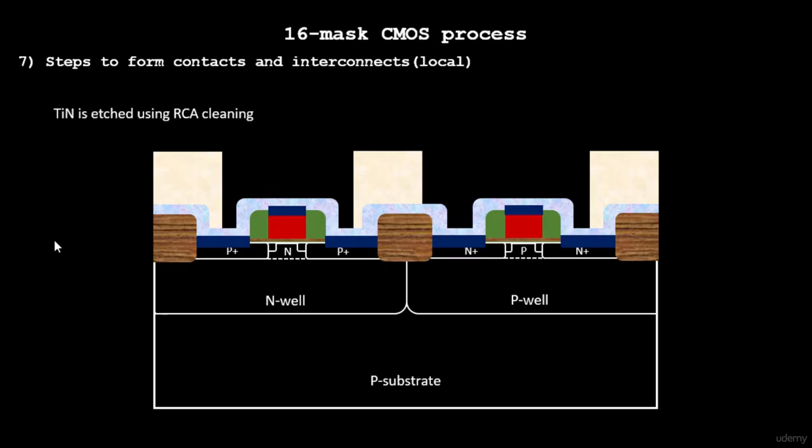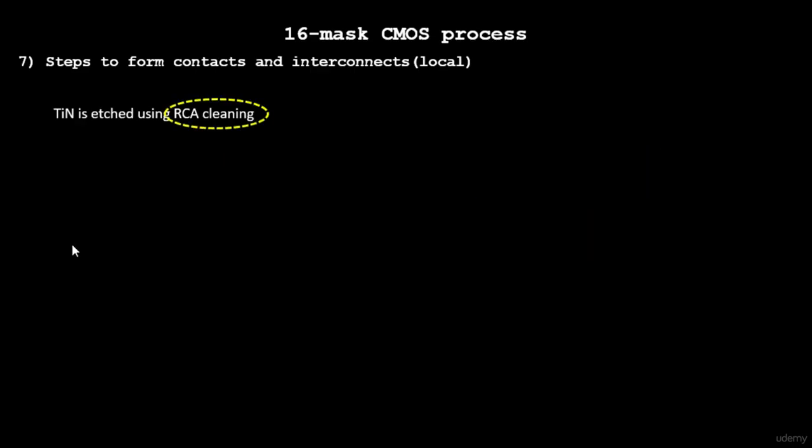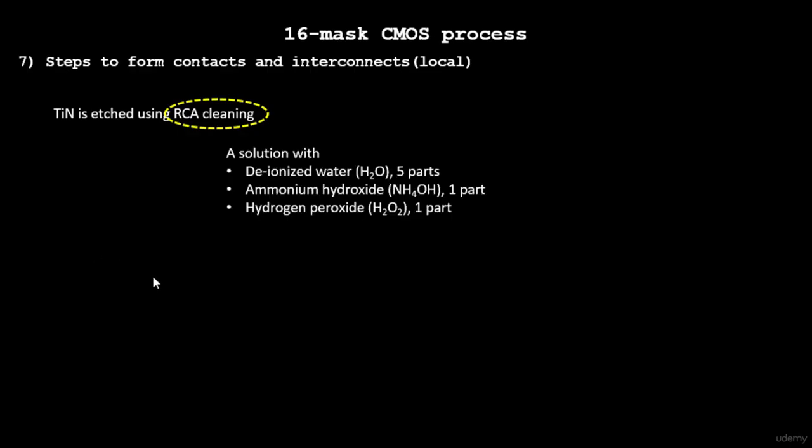Now you see the structure over here, the LDD, the lightly doped drains, are still maintained. There is some amount of N minus implants present. Now these are the N plus implants that we just did using arsenic. So in this case, we have a source which is N plus, an LDD which is N minus, and a P-type area over here. This is the kind of structure that we actually needed, and we discussed in the past video.